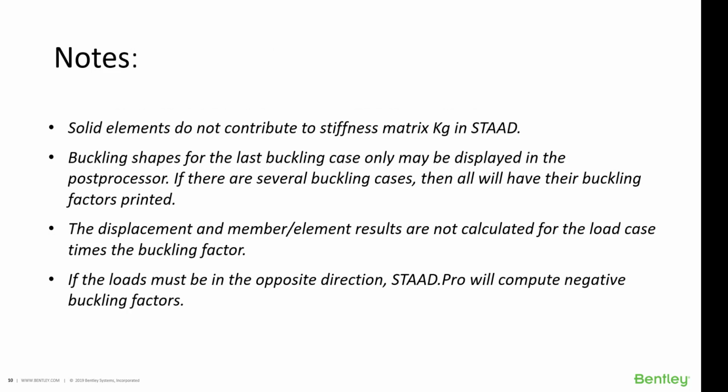There are a few notes about advanced buckling analysis in STAAD.Pro. Solid elements do not contribute to stiffness matrix in STAAD. Buckling shapes for the last buckling case only may be displayed in the post-processor. If there are several buckling cases, then all will have their buckling factors printed. The displacement and member element results are not calculated for the load case times the buckling factor. If the loads must be in the opposite direction, STAAD.Pro will calculate negative buckling factors.